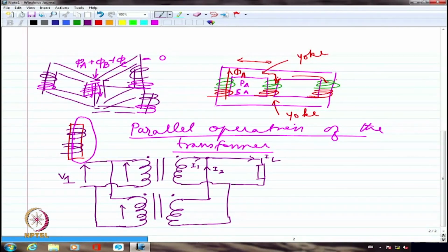For example, I may have two transformers of 1 kVA each. I might like to supply 1.5 kVA to a load. So maybe I would like 0.75 to be supplied by one transformer, and another 0.75 by the other. So I have the leverage to go up to 2 kVA. Maybe I will have load variation right from 1 kVA to 2 kVA. That's the reason why a 1 kVA transformer was not sufficient, so I had to necessarily put in one more transformer. So that gives the answer indirectly.